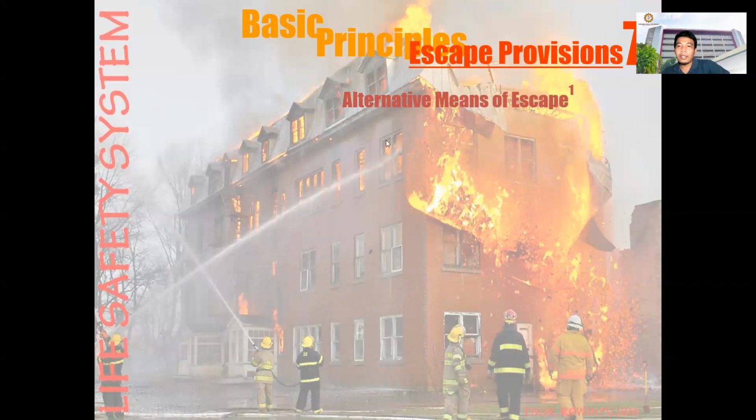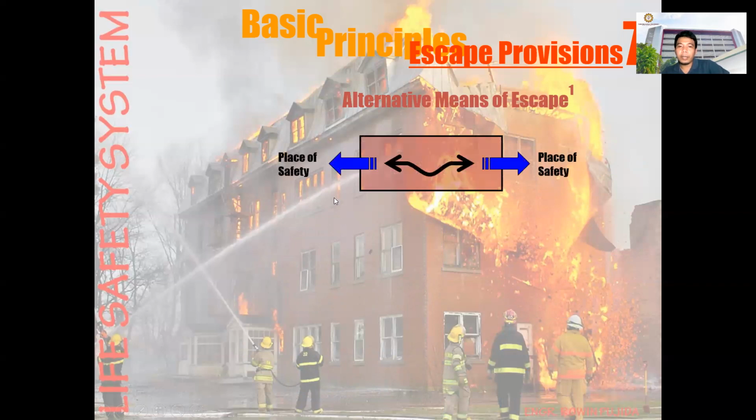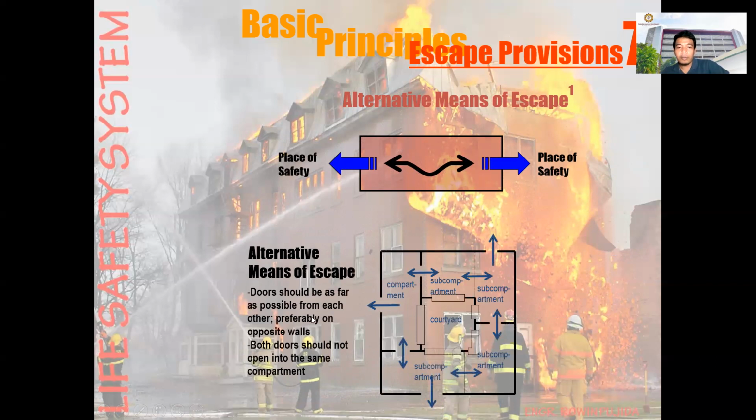Also, we have alternative means of escape. You have the place of escape. The alternative means of escape doors should be as far as possible from each other, preferably on opposite walls. Both doors should not open into the same compartment. Example: compartment 1, another compartment, and another subcompartment. The doors should preferably open on opposite walls, and both doors should not open in the same compartment.